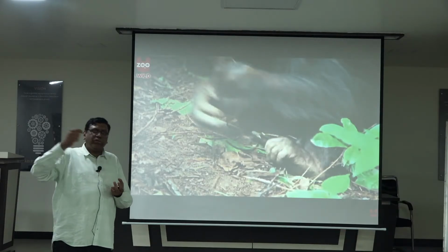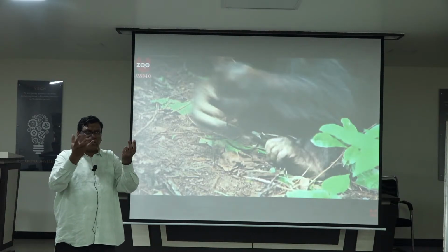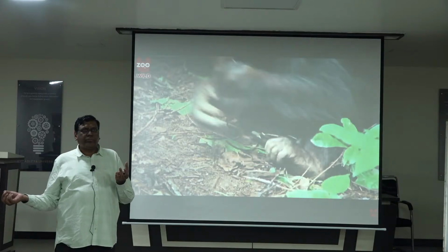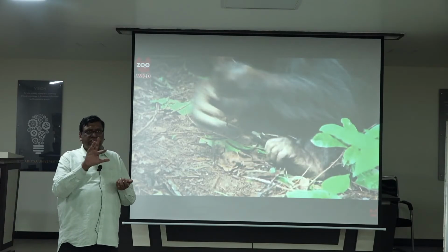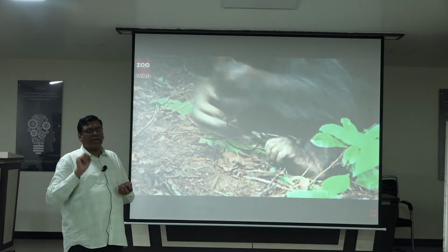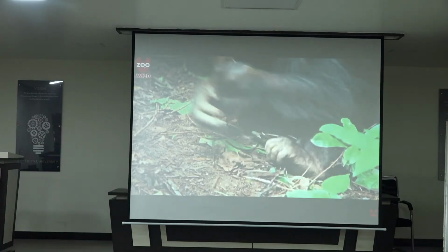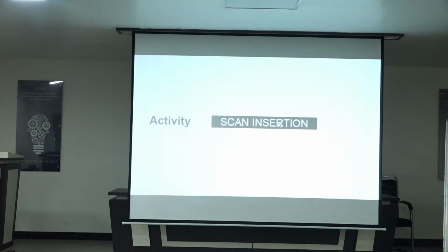Then we will shift out the data. So the data that is being captured by internal nodes, everything will come out from the primary output. So shift in, capture and shift out. These are the three activities we will do to capture the internal node data values. Okay. Next slide. Yeah, come next.